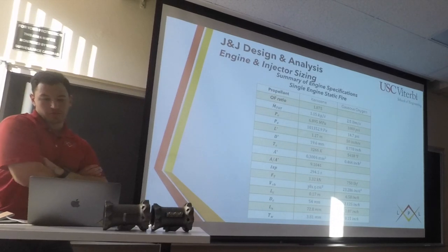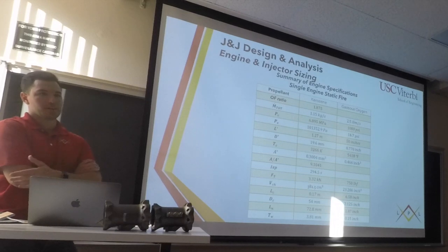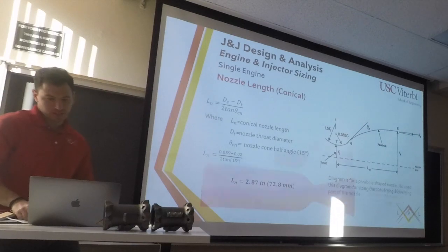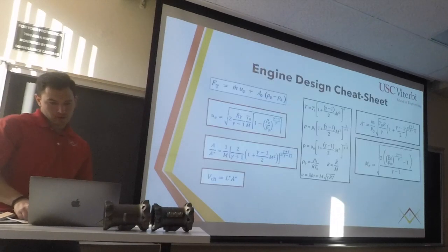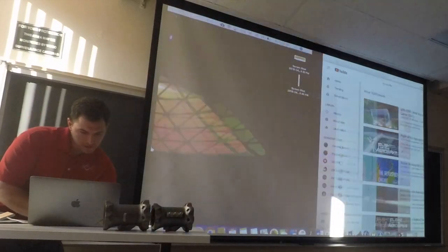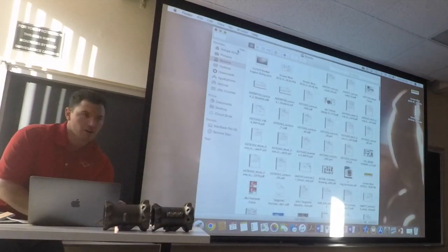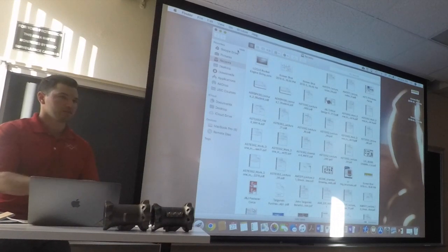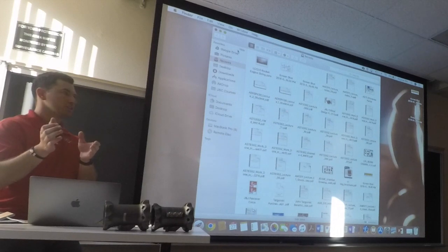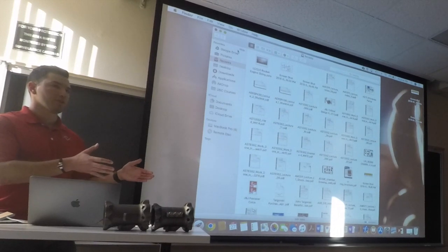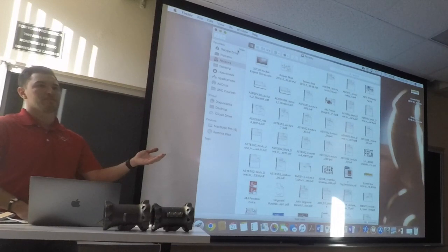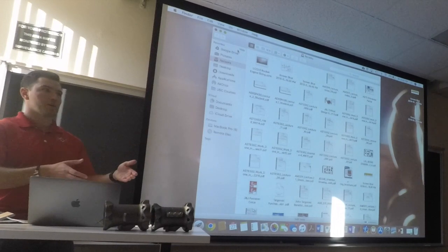Yeah. I mean, for those specifically, we could pull up the code that Mike and I did for the class, but that's what the whole design point is. This is a more simple consideration, so might as well just pull that up. This is a very simple consideration. Our design point was the pressure and the mass flow rate. That's it. And that ends up with a certain temperature. And so technically, if that's your design point, you go into it, and then someone is like, crap, that's too high of a chamber pressure, I can't cool that. And then now it's like, all right, well, how do we get a lower chamber pressure?